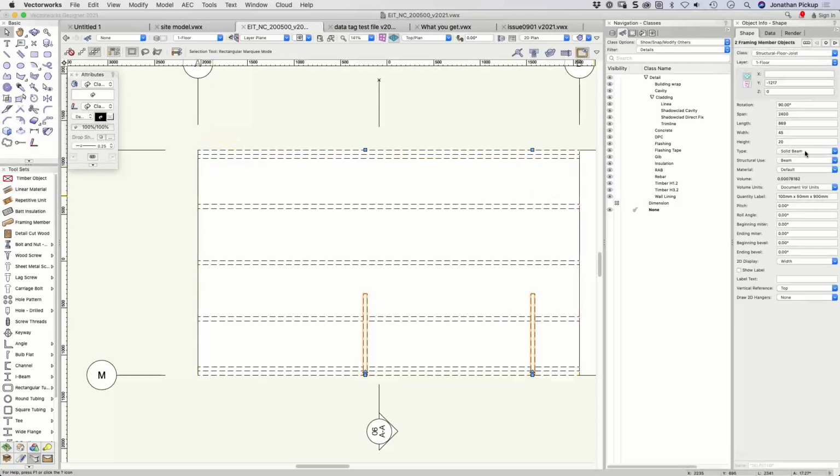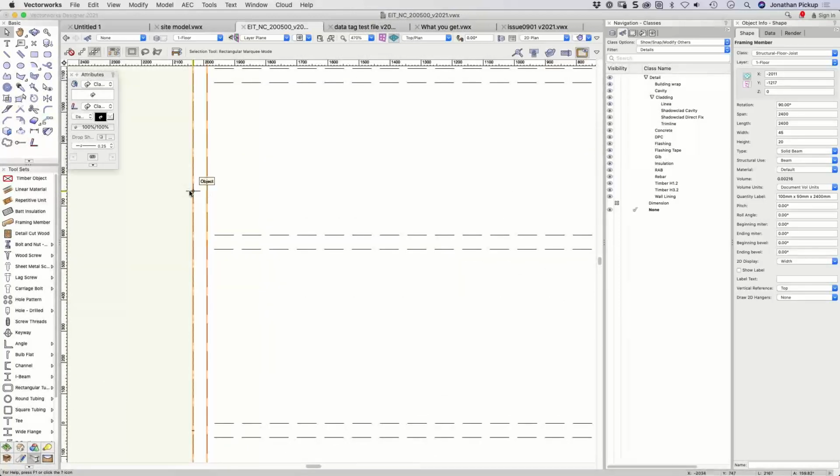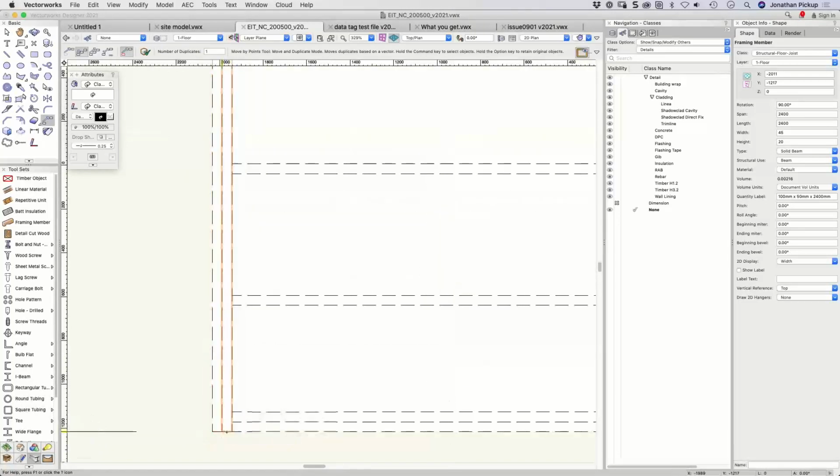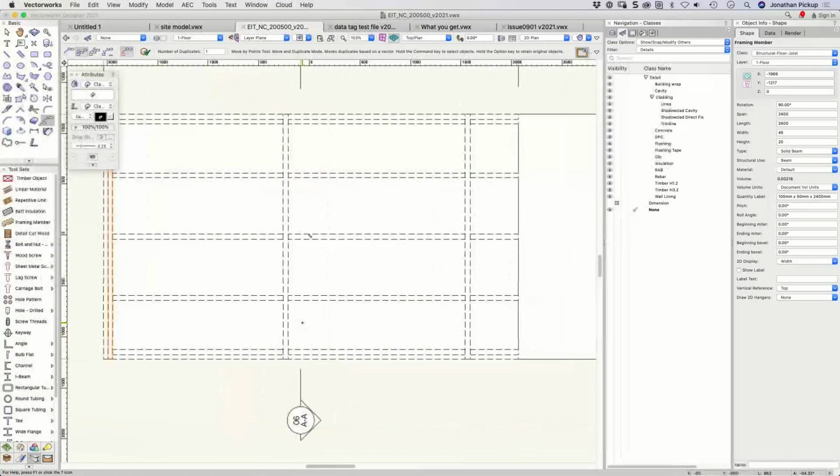And it's created those two there, which again, I'm going to make a solid beam and then drag a copy of this one along. Don't forget, you can just drag those. And I want to duplicate that because I want 2 of those. Yeah, I do need 2. So again, I'll use my keyboard shortcut from there to there. And then I can go, I think it's Alt on a Windows machine, it's Command on a Macintosh. I'm going to frame from that corner to there and do the same thing here. So grab that one.